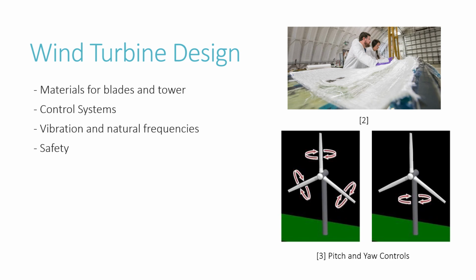To avoid this, vibration damping mechanisms such as tuned liquid dampers or pendulum-tuned mass dampers are used to either mitigate vibrations or move the vibrations to a different non-resonating frequency. Vibration-absorbing materials may also be used in the structure to limit the effects.